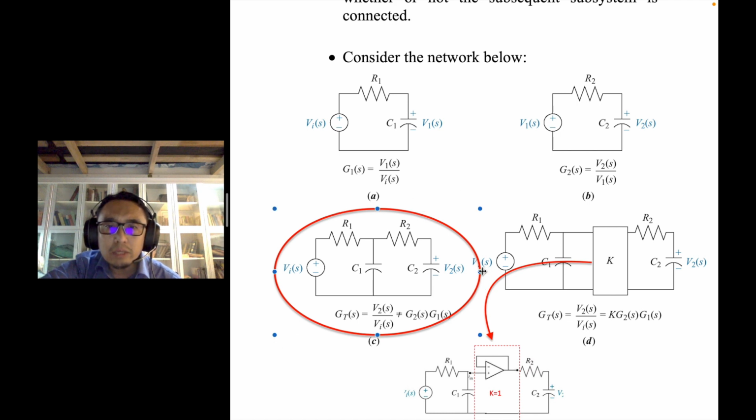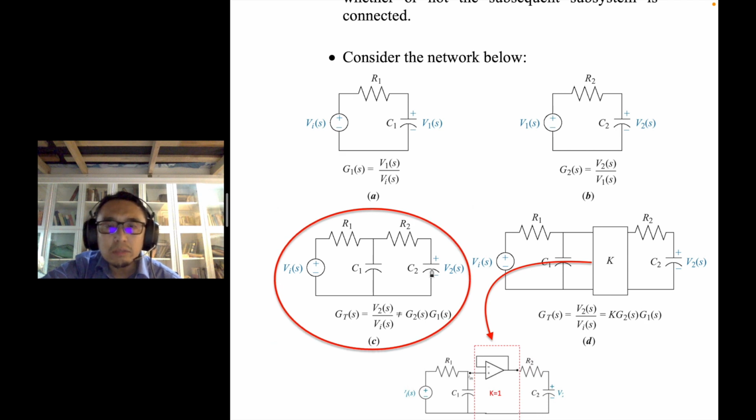then you will see that the cascade rule will not apply here, because if you connect these two circuits together, then loading will occur.